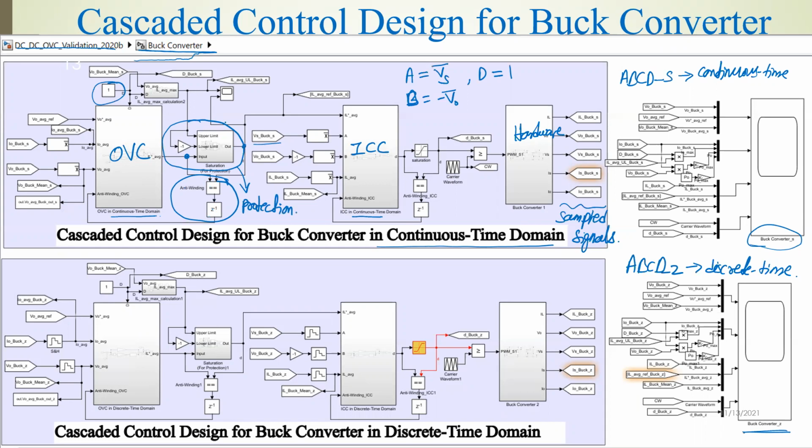So here we would like to saturate our inductor current reference value, so that our converter never runs into an unstable or very high current operating mode. Inductors are rated for some current, so we should not exceed it, we should not make more current flow through the inductor, especially during faulty and overload conditions.